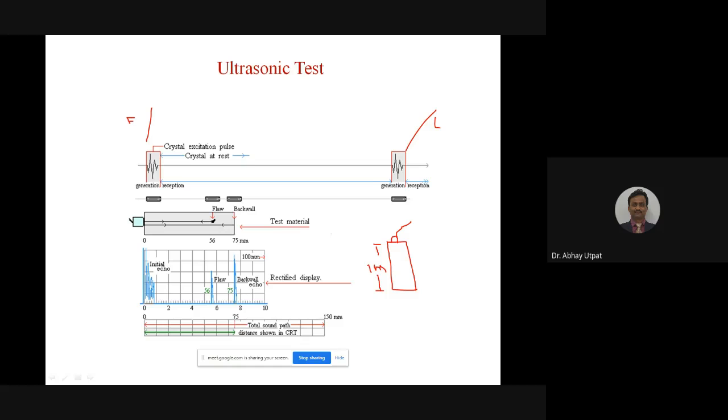So if you get these signals every time for a 1 meter component, which is a standard one, then every time you will get a peak, or you can say every time you will get the beep. Peak is the value here which is shown, and if you are getting it after every particular time, suppose 10 seconds, it means the part is standard, it is not having any crack. But if here is any crack,